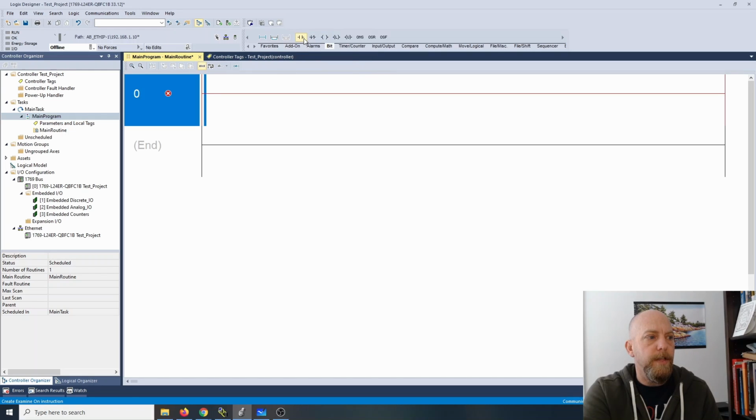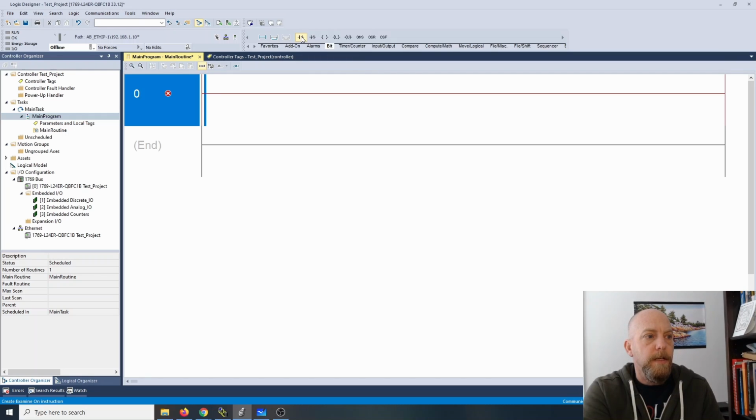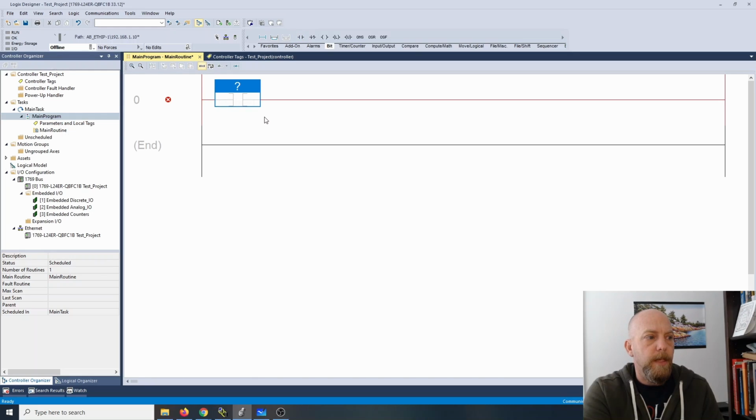Okay. For either of these guys, similar to all the other videos that I've done before and all the other PLC programs, you grab these guys, hold down your mouse, and then bring it down to the rung. And when you see green, then you can let it go and it drops in. Okay, so I've got an XIC here. I need an output on the end here, so I'm going to drop that bad boy down here.